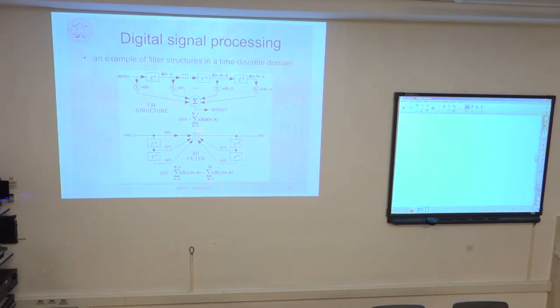And the difference equation that completely describes this operation is this summation shown with this equation. Y of n is simply a weighted sum of x of n minus 0, n minus 1, and so on, up to n minus capital N minus 1.